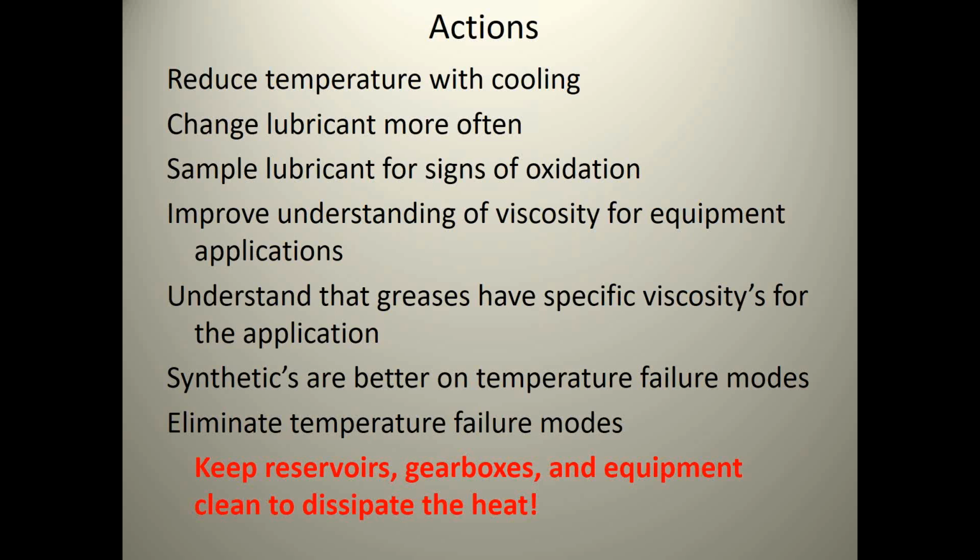Some people think in oil analysis you have to always send a sample into a lab. Well, one of the things I used to do for oxidation, I would buy those round filter papers that you get for a lab, put a couple drops of your lubricant on that filter paper, let the oil start expanding through the filter paper, and then put a date on those and keep them in a Ziploc bag. So as the oil gets dark, you can just compare it month to month. When that oil gets to some point where it's dark, then it tells you you need to change it.